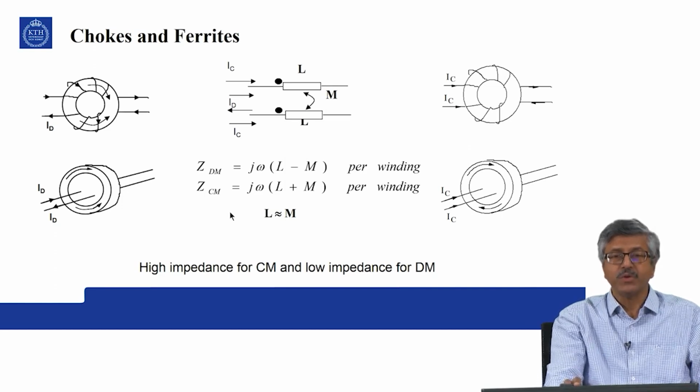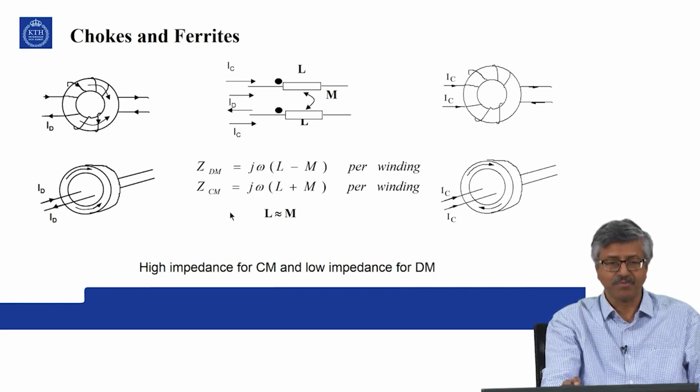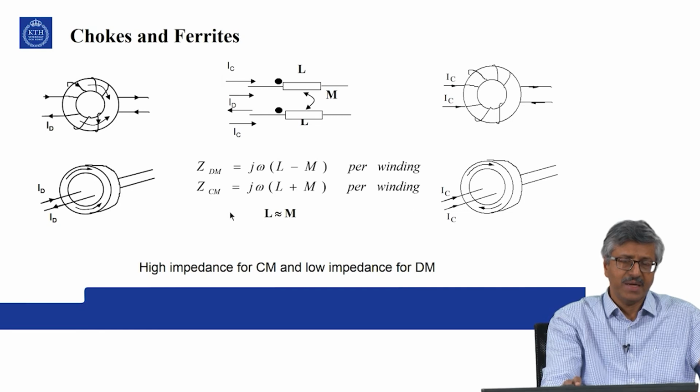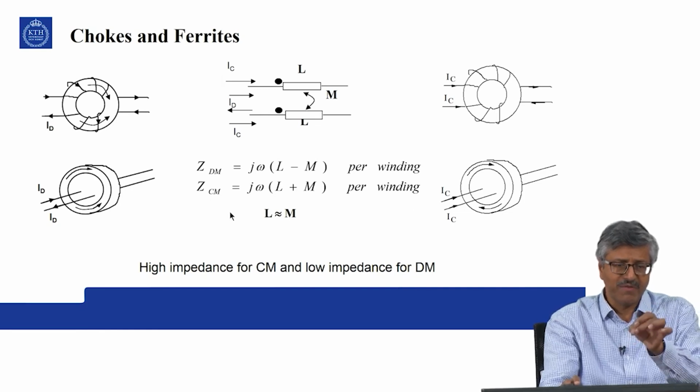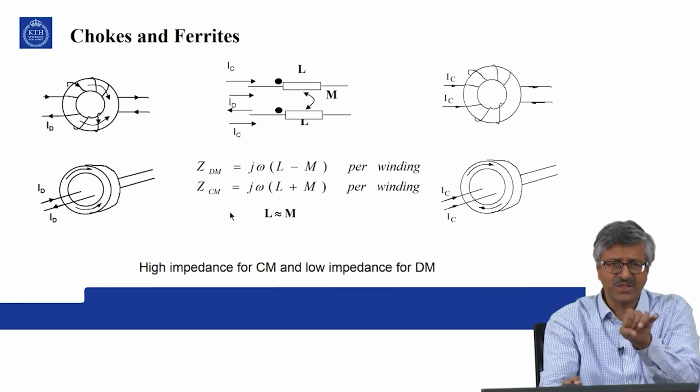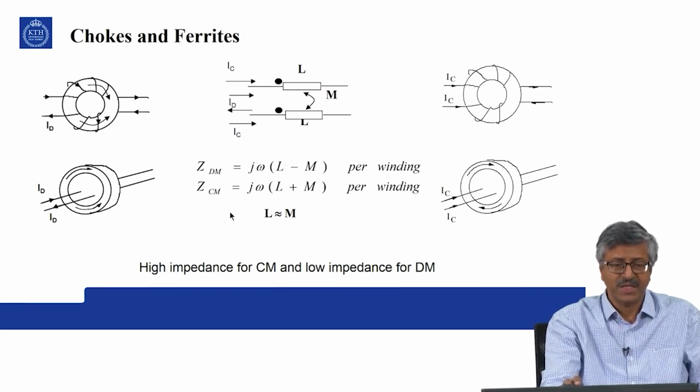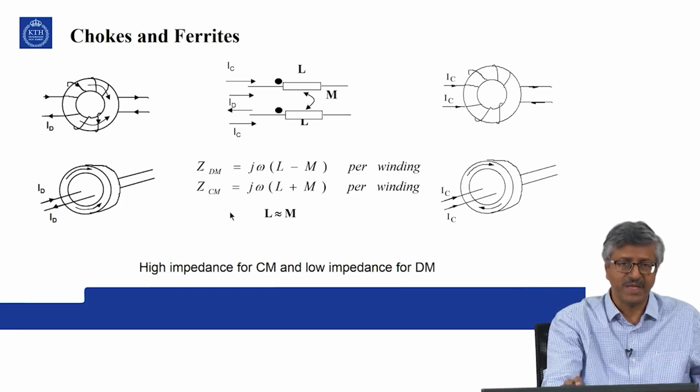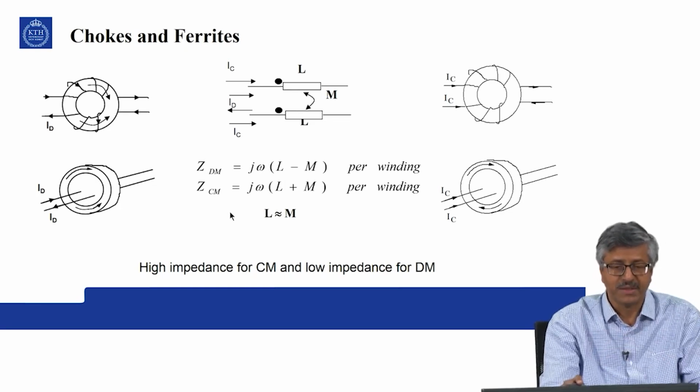And often we use chokes and ferrites in electronic components. If you connect a monitor, sometimes you can find a round heavy thing on the cable itself, and that is a high frequency choke. This is for filtering out the noises coming from the supply, or for preventing the noises going from your device to the power lines.